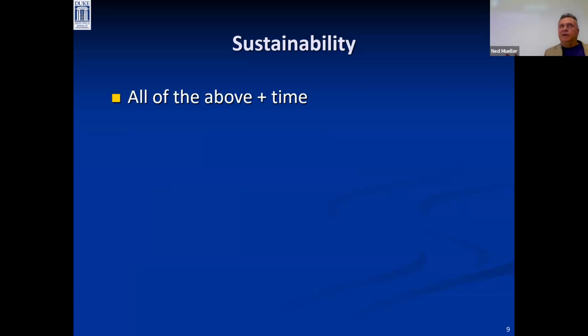So if you look at a reliability plot, for example, you'll see the famous bathtub curves. We have early failures, late failures, and then you have that optimal range in time. When you design a system, it needs to work for a designed time. For something to be sustainable, you need to stretch out that optimal period. And it is a response, so it does have both a space and a time component to it.